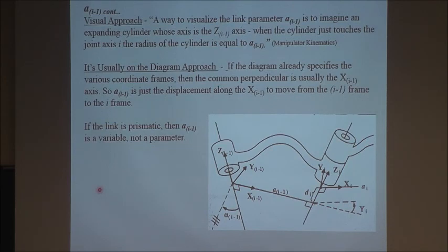If you are looking at a Stanford arm which has a prismatic joint called in and out, okay, there is no rotation attached to it. Therefore, the DH parameter coincides with the variable itself. It's sitting on the same line between one joint and another joint. Imagine that this joint is connected to the other. Earlier in this slideshow, you saw a robot which goes in and out of a cavity. Okay, that is going from one joint to another joint.